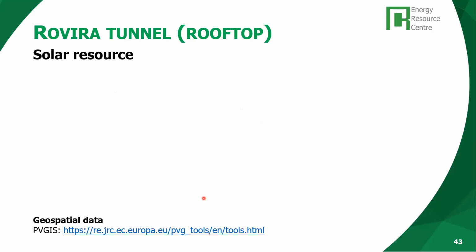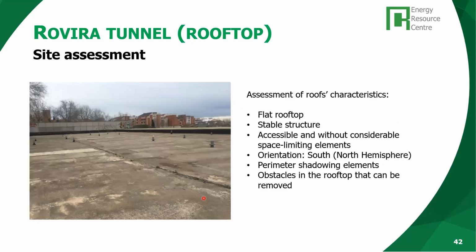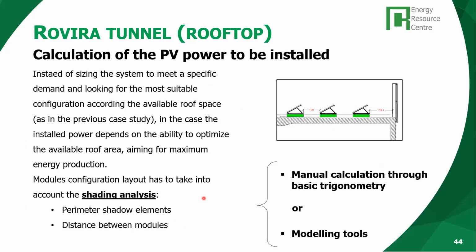Of course, in a surface like this, now you have to think a little bit how to place the modules, right? Because you can put many of them, but you need to be careful with the shading between the different lines. Yes, we have to calculate very well the separation between the lines. At the same time, we want to produce as much energy as we can, and in this case, the client wanted to take advantage of the space a lot.